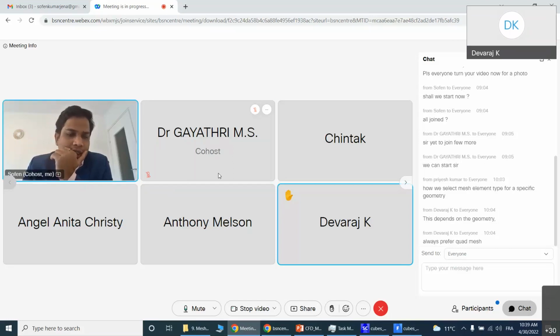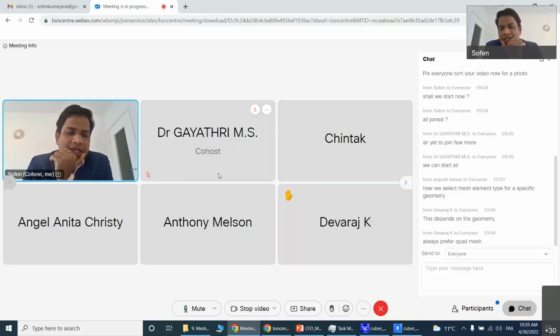There is no limit for you to go to refinement. There is a limit of hardware, meaning how many million mesh count your hardware can handle. As a thumb rule, on average, 1 GB memory is required to handle 1 million mesh count.